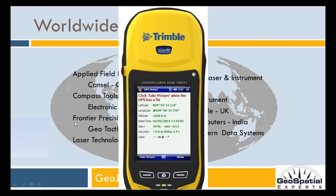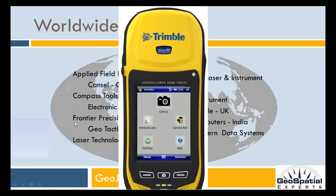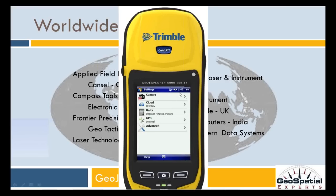Hey Tyler, another question about accuracy is, to get better accuracy, can you use Bluetooth with an external antenna? Yeah, definitely. Same way that I connected that laser device, you can connect an external GPS device to the GeoJot system. Here within Windows Mobile, if you have an antenna or an external GPS device connected, you'll see on this screen in settings, the GPS is set to internal right now, but you can click that and you can change the GPS port.